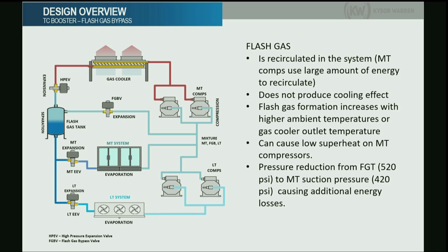Still like a 20-minute hot gas defrost? Yeah, it will be similar. Wouldn't you put a lot of stress on those coils? Yes, that's why we do not recommend hot gas defrost, but there are some customers who want hot gas defrost because they have been using hot gas all the time. With CO2, it's actually more stress than HFCs. But this is what the customer wants. Until now, all our systems are only electric defrost. We are doing the hot gas because it's a requirement.